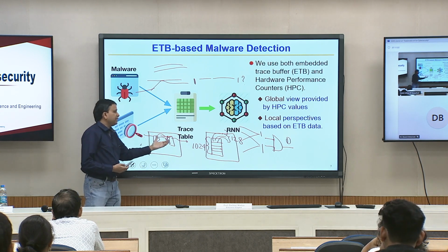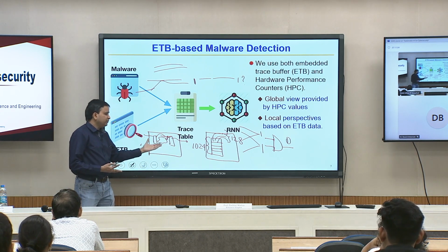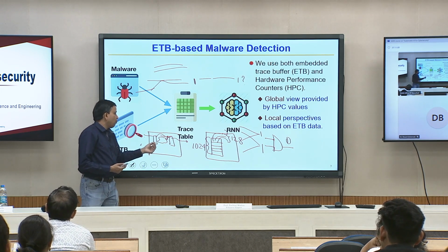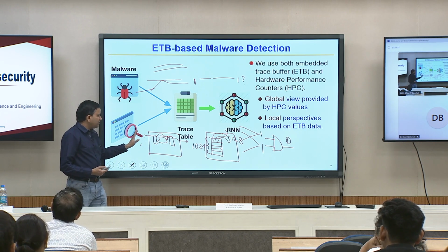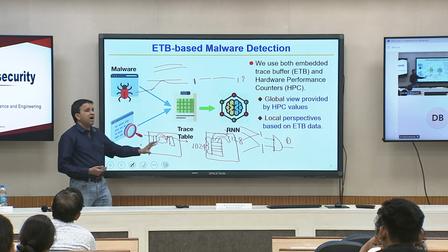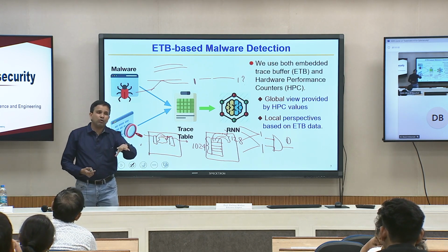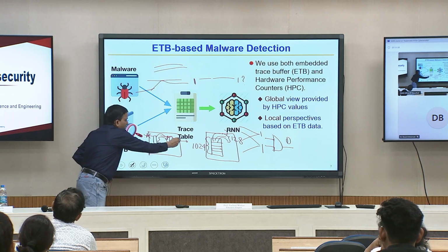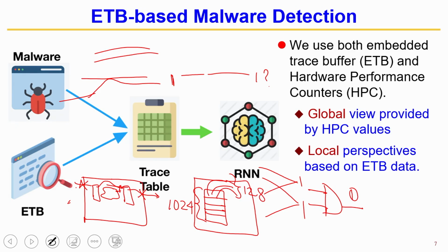So, that is why around 2010, 2015, the solution was, well, once this manufacturing testing is done and the chip is placed on the robot, this would be sealed, so that we will not have a mechanism to push anything in from the scan chain and push anything out. Then people found a problem with that. A lot of solutions are in between, but these are the structures that can be used for malware detection.